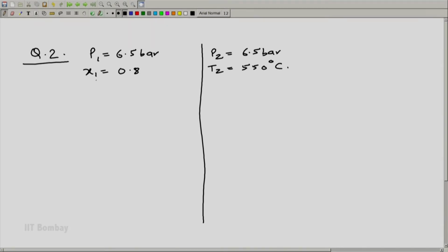This is the data. So, after interpolating the values at 0.65 MPa, we will calculate the values for the given x value of 0.8. So, we get V1 is equal to Vf1 plus x times Vfg1. Similarly, we have values of H1 and S1.